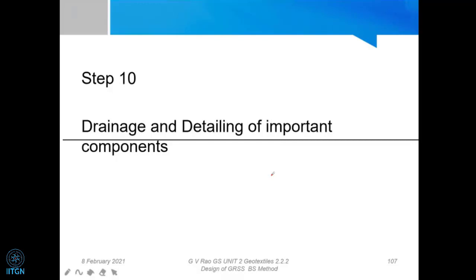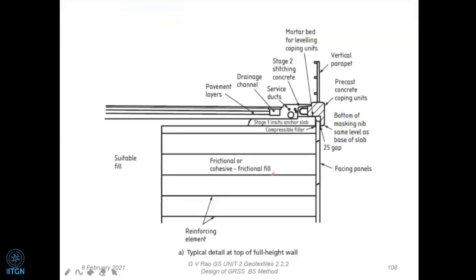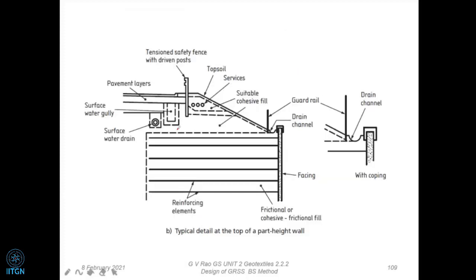The other thing which you'll consider later, when you come to filtration and drainage, is that the detailing is going to be very important. The detailing is done in such a way that during construction, no water enters the wall. Okay, if water enters the wall and you finish the capping, this water will remain there. If it's going to remain there, we have to take care of the weight also. Bulk unit weight we take, not the effective unit weight.